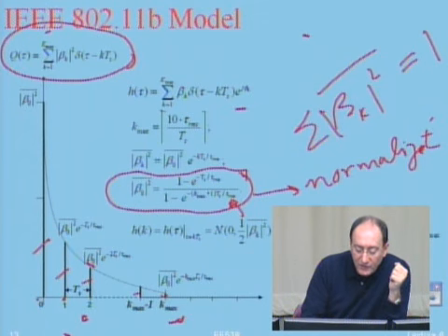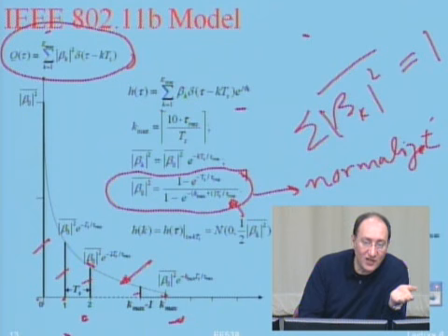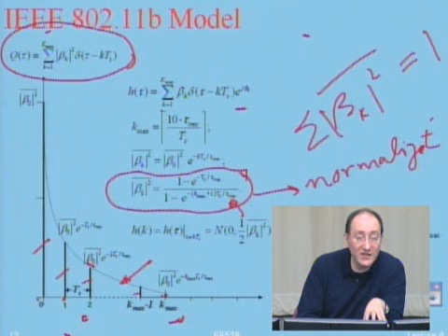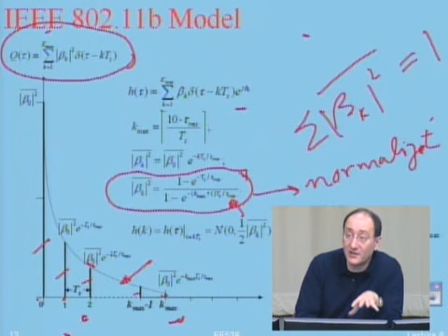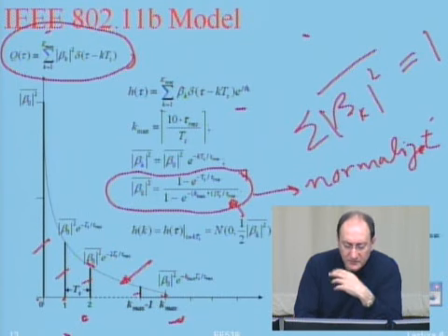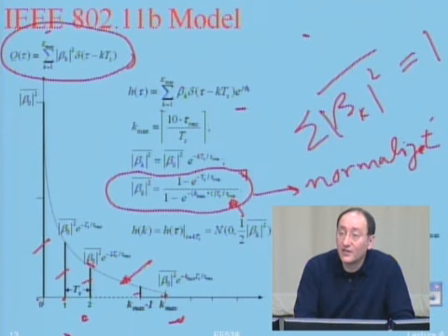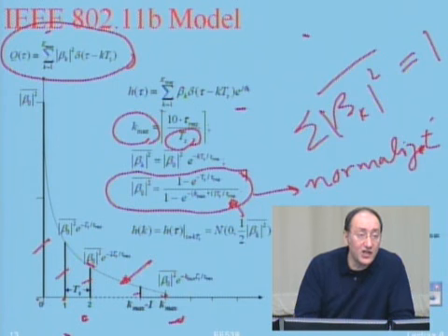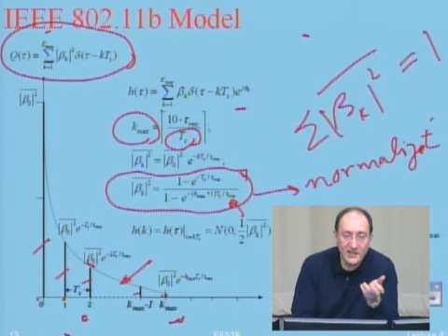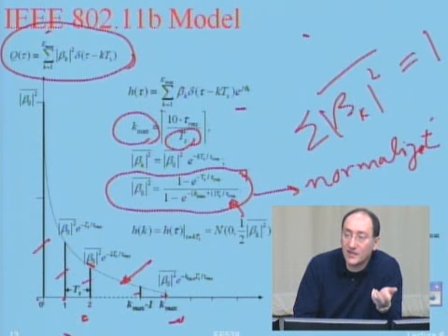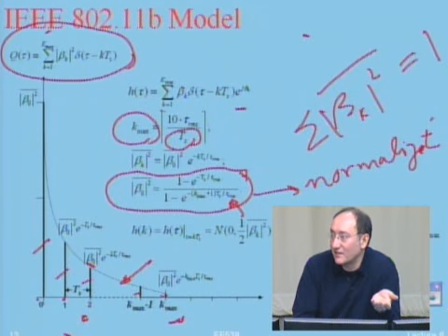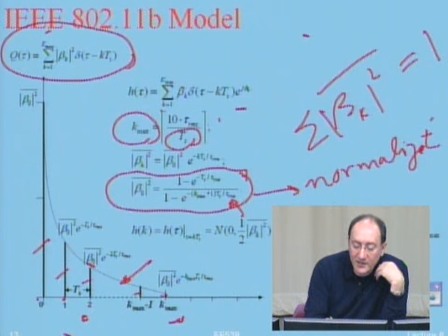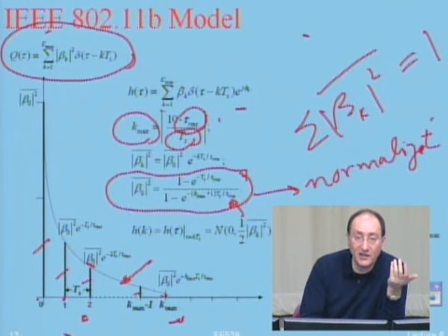Why they are, who told them that it's decaying exponential, they go after this Saleh-Valenzuela's model. So it's a sort of fixed form of Saleh-Valenzuela model that I will show you a little bit later. Now, so it's very clean, neat. You know that how many samples you have. It depends on the TS. TS is on you. What is the tap delay line of the device that wants to implement this? That's TS. TRMS is something physical associated to the building.